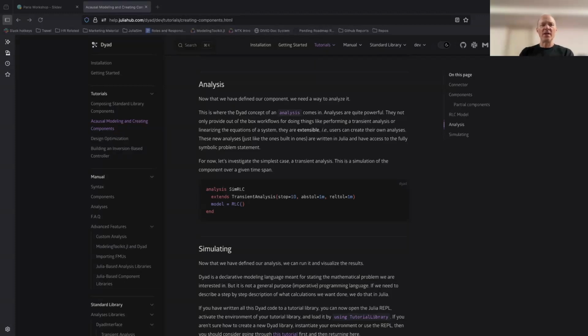They really aren't. So what you'd need to do in that case is, oftentimes when you deal with something that has multiple components in it, you have to identify upfront, there are n components in this fluid, right? And so the way I would approach a problem like that is I would figure out the total set of components that you have to worry about, whether it's backward or forward. Then create your media properties in such a way that you take all of them into account. So if I have X mass fraction of this and Y mass fraction of that and so on, what is the density of it? And then bidirectional flow doesn't introduce any changes in media. It's not like it's a different media, whether it's flowing backward or forward.